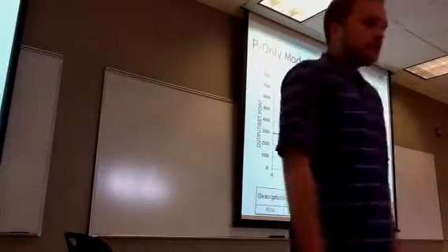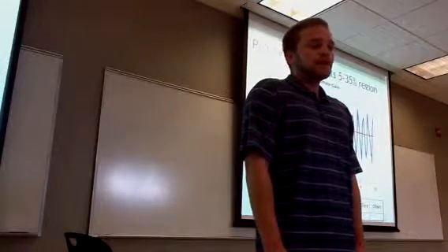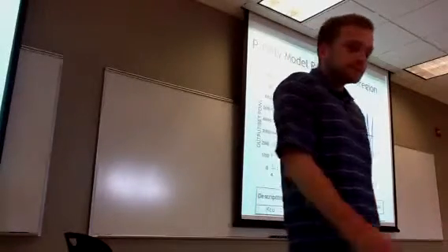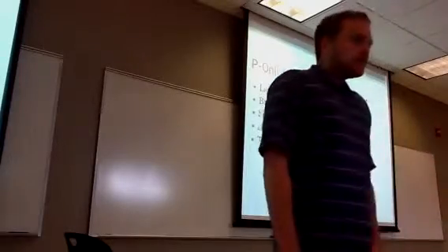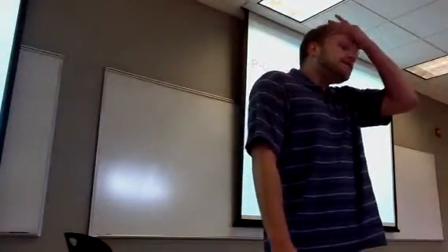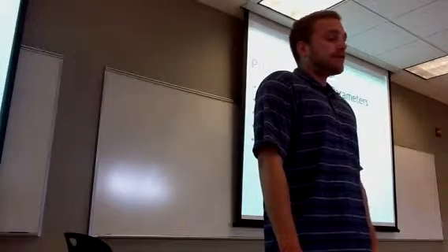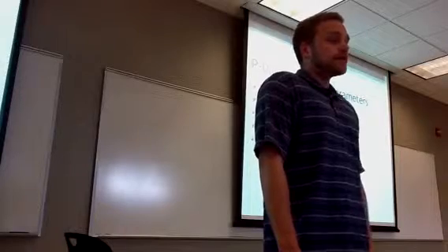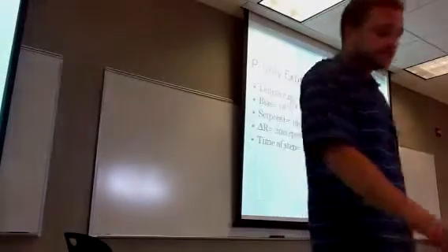Here's the ultimate gain, and you can see that it's oscillatory with a controller gain of 0.474% per RPM. The P-only experiment parameters gave us, the time was 20 seconds with a bias of 18%, set point of 300 RPM, delta R of 200 RPM, and the time of step was 10 seconds.